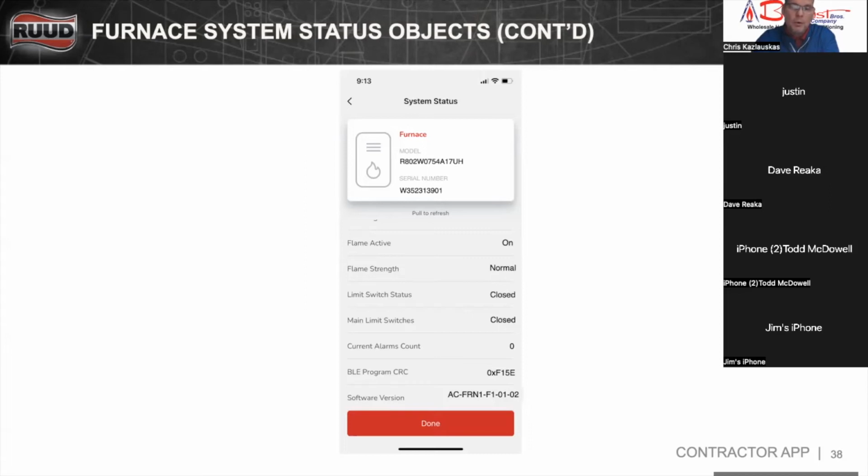No more yellow blinking lights, none of that. If they want to know their flame sense, they're going to have to use their app or their EcoNet thermostat to see that in the new M1 product. That is a digital signal now, and it's something we need to remember when we're talking about getting them to use the app. That's going to be key. A lot of these guys are going to need the app to read that and understand where they're at on the flame sense. So, moving forward.